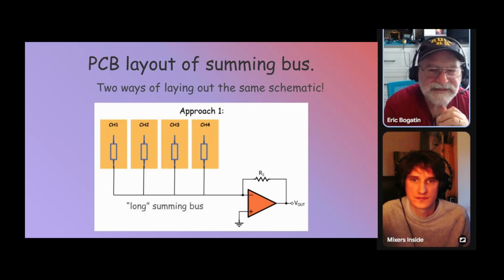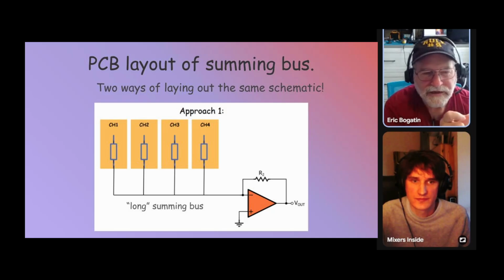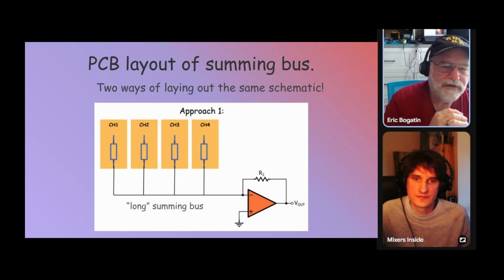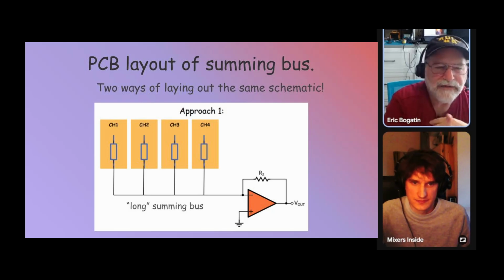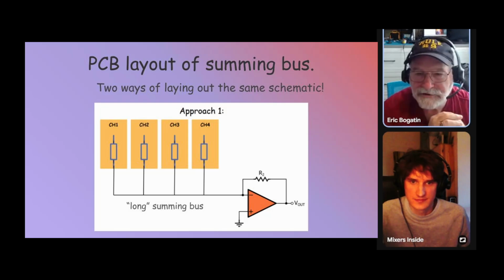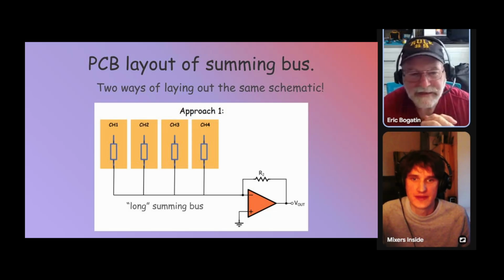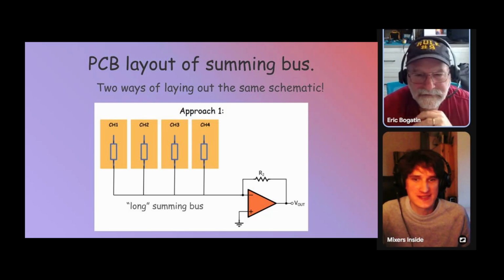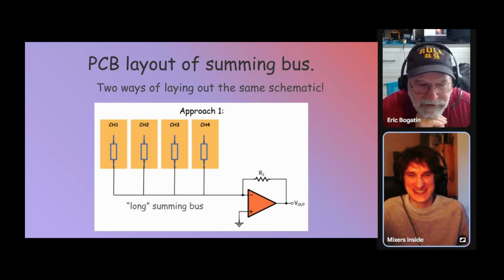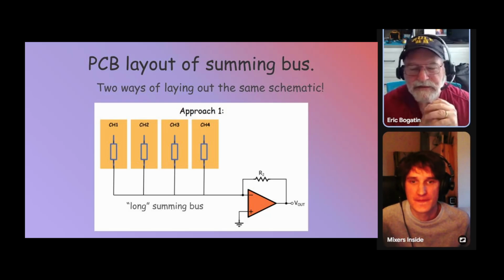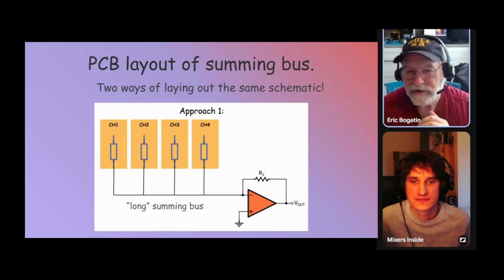And so you would want to have a separate return conductor, another wire, for that ground connection, so that the ground wire in the cable is not part of the reference structure here. And it's basically a differential signal. That is what you're trying to do, is make it differential. So no excuses. Right. Doesn't work. Because you're always going to have a voltage difference across the ground conductor because of not so much the IR drop, but the inductive crosstalk as well.